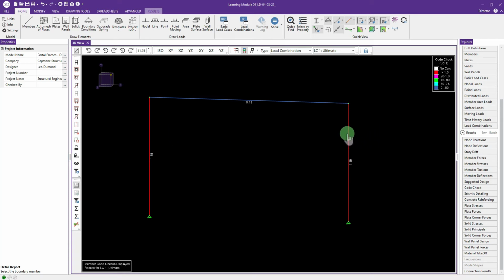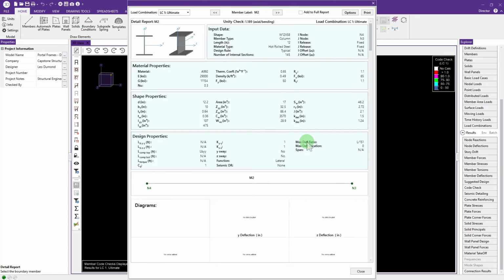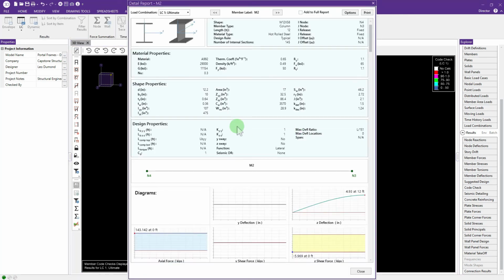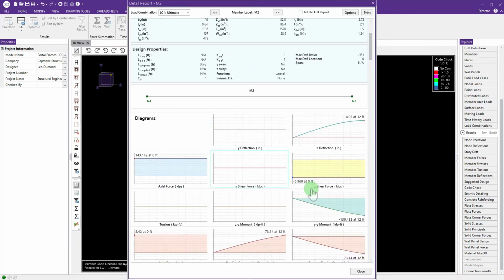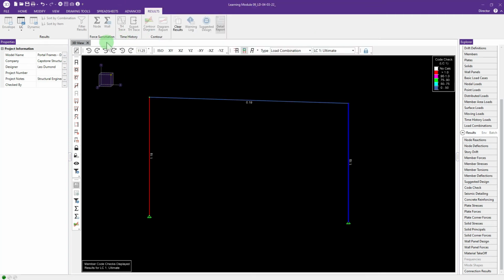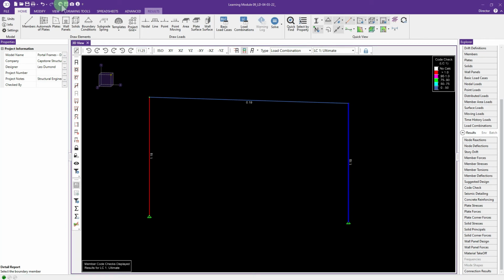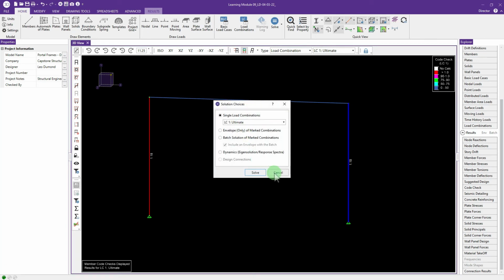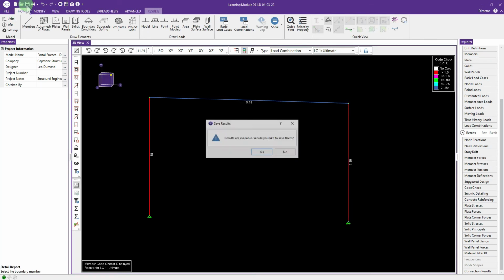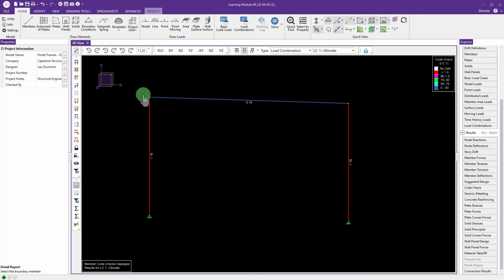I click on this one, 136.65. Oh, I kind of screwed up a little bit, so we can go back and correct that. And what I screwed up, this is 130. So where I screwed up, and I'm glad I did, so to speak, is that I haven't modeled the imperfections. Cancel the out of plumb imperfections. So I need to do that.